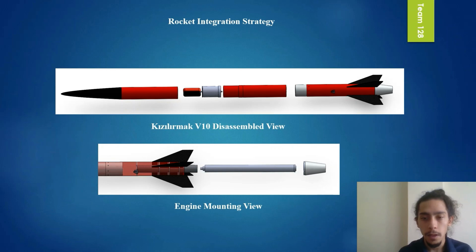After assembly, the shock cord of the main parachute was connected to the avionics section, and the engine section was placed inside the main parachute section together with the parachute. The main parachute section and the motor section, which are separated from each other during the flight, were assembled together with the aluminum connection part, which was also used as a bulkhead.